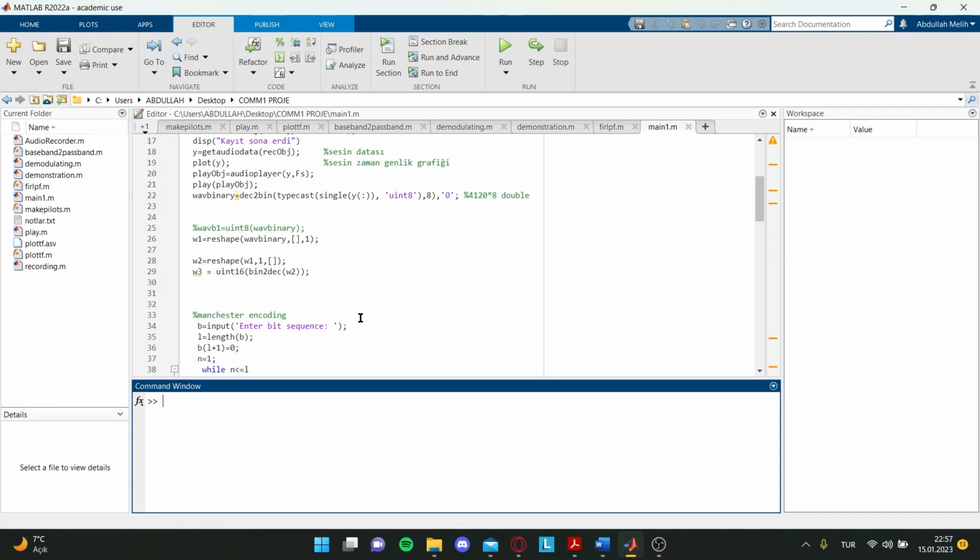SZ must contain at least 2 elements, and prod(SZ) must be the same as the number of elements in A. You can specify a single dimension size of empty to have the dimension size automatically calculated, such that the number of elements in B matches the number of elements in A.